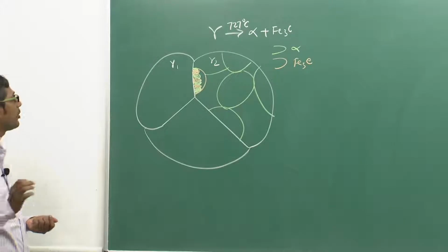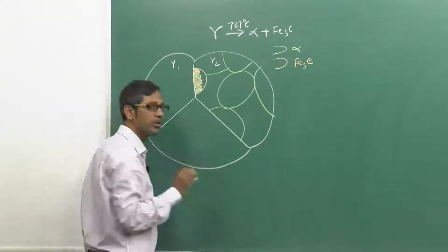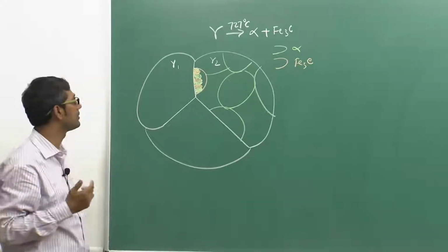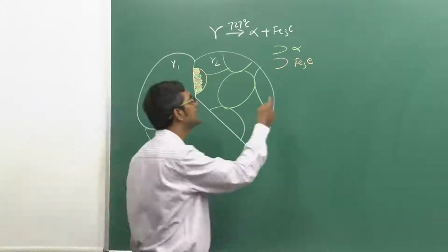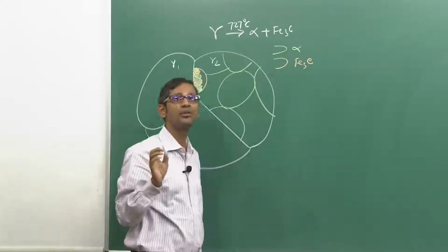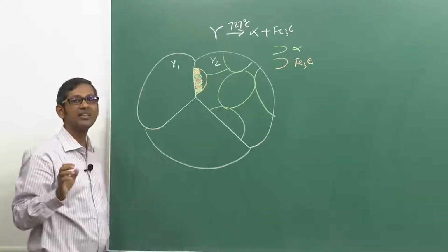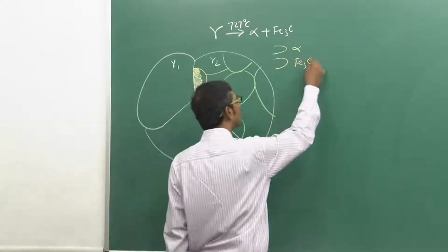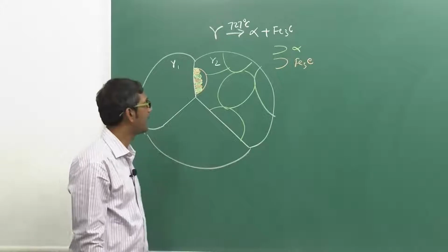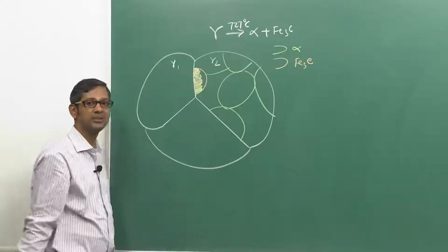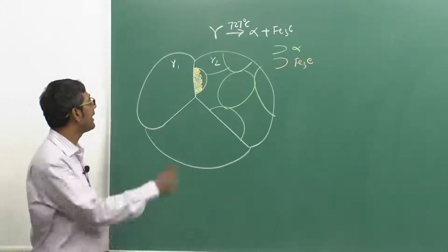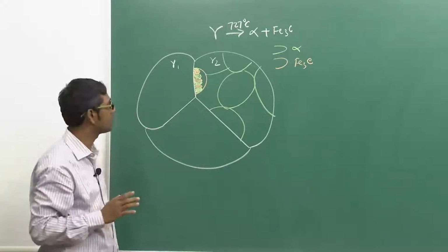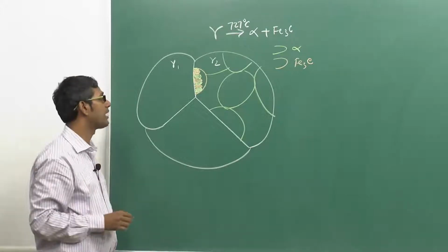So, the most important thing which controls this transformation is the carbon diffusion. As you know, carbon is an interstitial species because it is a small size atom. In BCC iron it goes into the octahedral site, in FCC it goes to the tetrahedral site. So, diffusion of carbon is relatively faster at temperatures below 727 degrees Celsius, and that is why these transformations are relatively faster as compared to other transformations in solid solution based alloys.